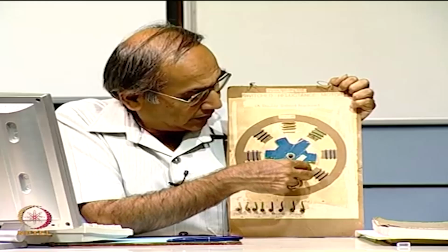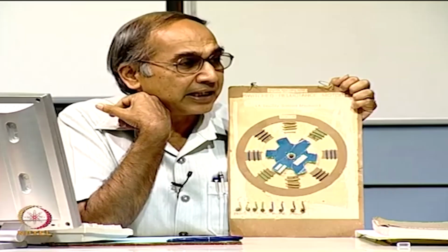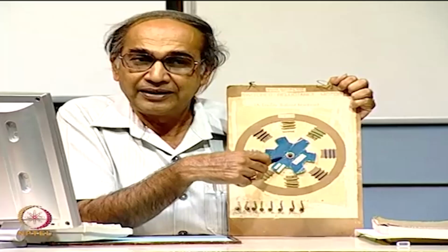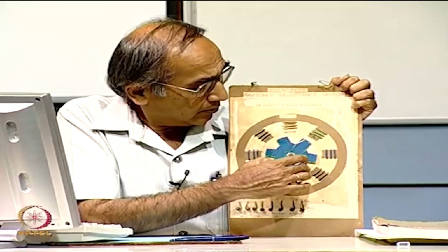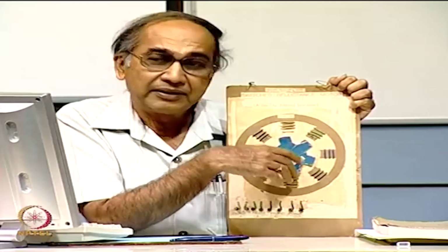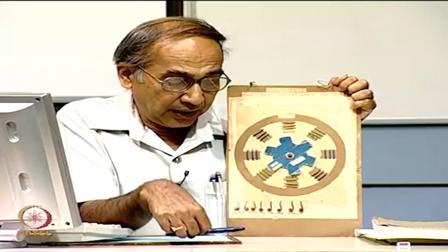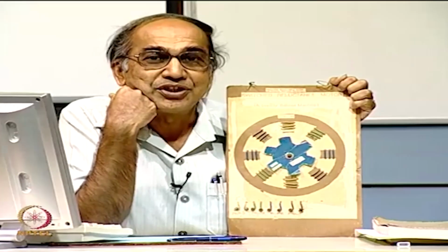So, this will go on rotating, and there is no coil at all in the rotor, rotor is just a variable reluctance. So, it is called a doubly salient structure, there is saliency in both stator and rotor, and there is a considerable air gap here. Okay.